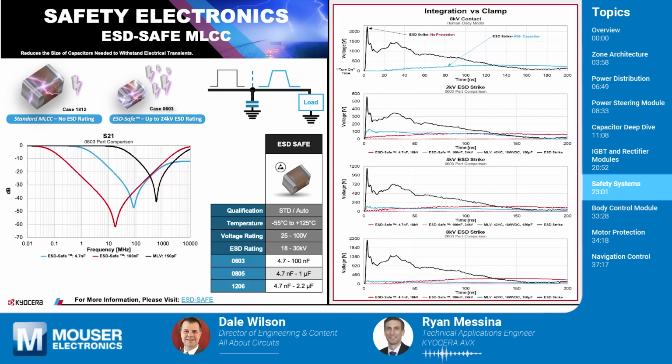And you can see from this graph, it's pretty neat. The black line on this graph is showing you an ESD strike. The one on top, I think it's 2 kilovolts going down to 8 kilovolts. So the black line is showing the ESD strike without any protection at all. That's just it going straight into your circuit. And then the blue line is the ESD Safe capacitor on that first one. So it's mitigating that entire strike and just absorbing it, eating it up, and keeping the circuit safe. And then for the 2 kilovolt and the 4 kilovolt for your human machine interfaces, you can see that the blue line is an MLV.